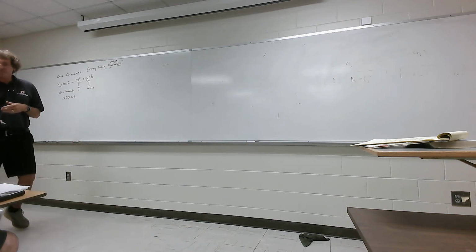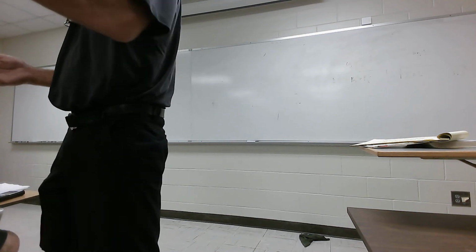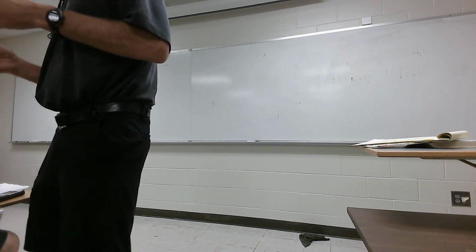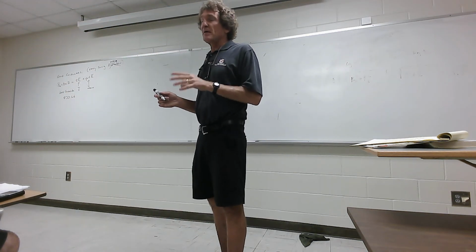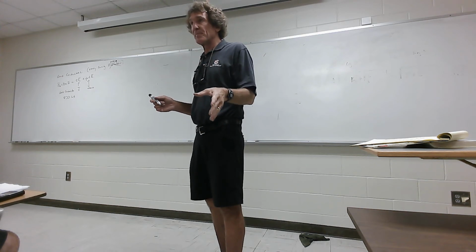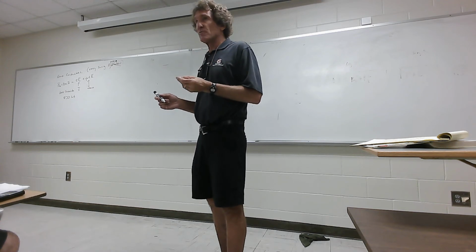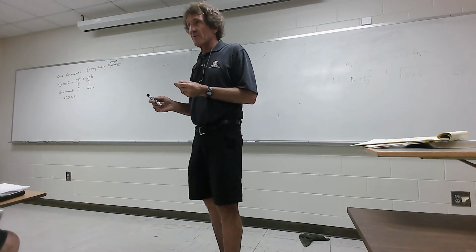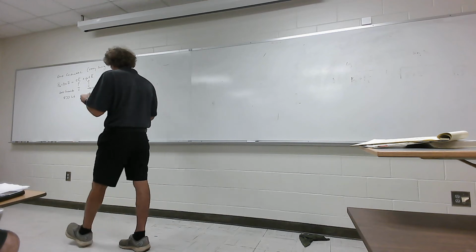In your mind, what comes to mind when I say, I'd like an example of a good conductor? Copper, probably the most common. Gold, right? Silver's a little better, not by much. And conductivity, by the way, electrical and thermal, is a strong function of temperature. I just want you to make sure you're aware that things that are good conductors at room temperature may not necessarily be good conductors at very high or very low temperatures. But we're talking about room temperature.